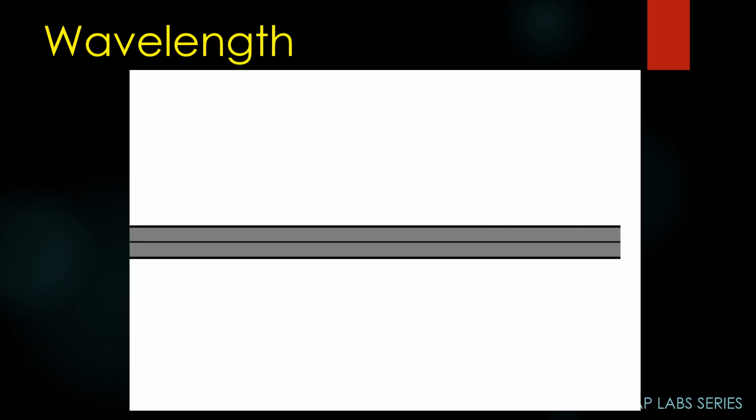All right, let's consider this piece of coax. It comes in from the left. We don't care how long it is right now. But you see on the right, it's open. There's no connector, there's nothing. I'm going to shove some RF energy down it. But the RF energy has no alternative but to completely bounce back. All the power is going to radiate back. There's nothing that can change that.